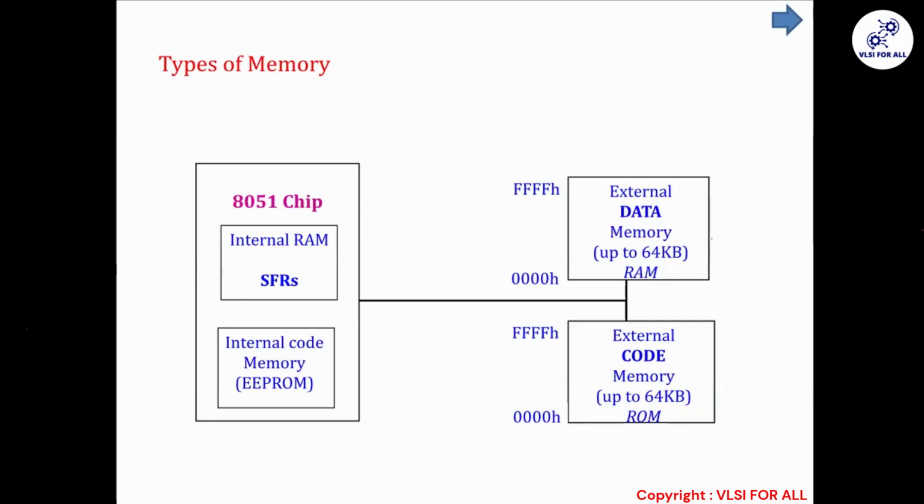So whenever it has to be separated out, whether I am going for address or for data, there is one pin called address latch enable. What is it doing? It allows us to shift from the address to the data. Once the address is given, for example, from this data memory, at some location, data is saved. I have to take that data.